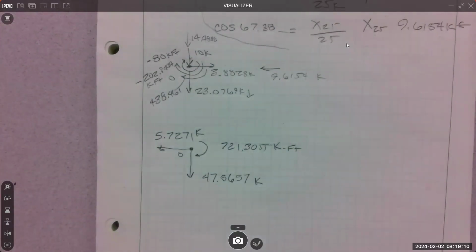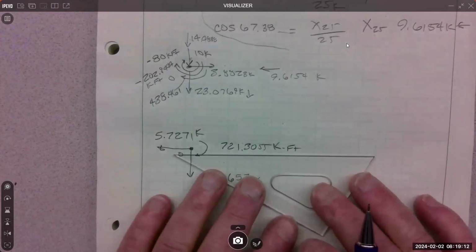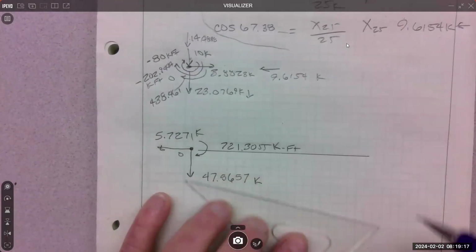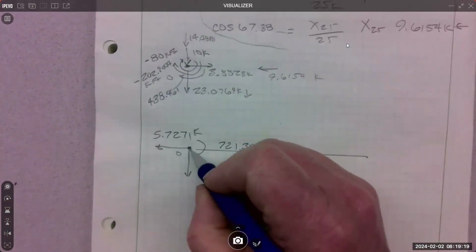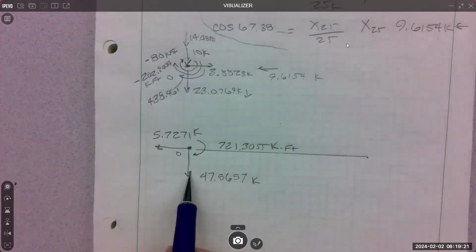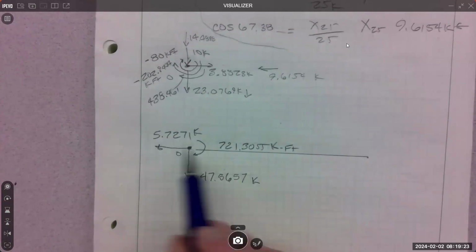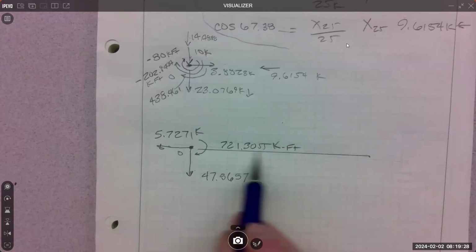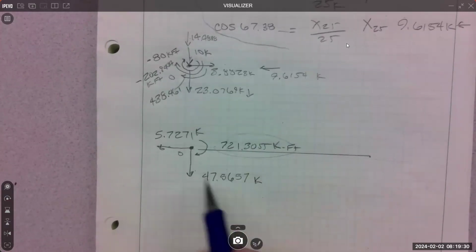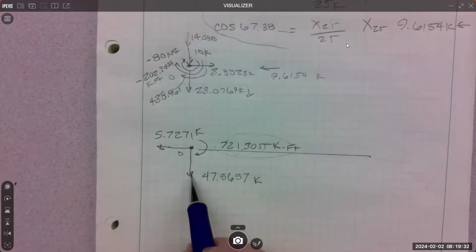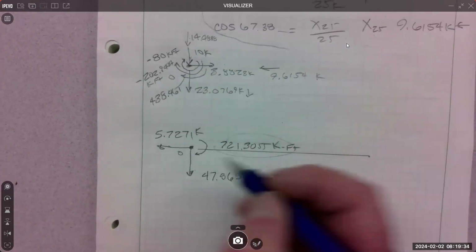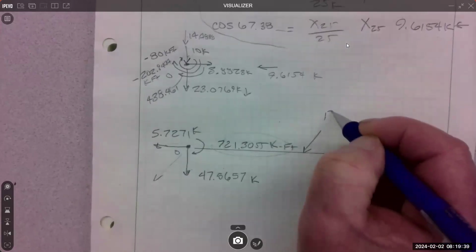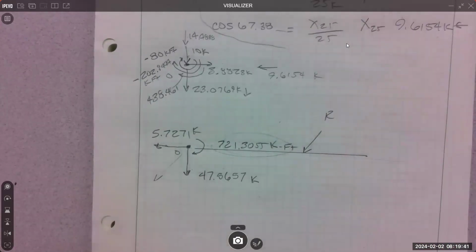So at this stage, I actually find out the location of the moment, or the location of the resultant. So here's my beam from here to here, because this is the force I use to get the perpendicular distance. I use that Y force. The X force does not contribute to that moment. That moment is created all by the Y force. And I know that R is down here somewhere, and so R is going to be out here somewhere. And I can get that from Pythagorean theorem.